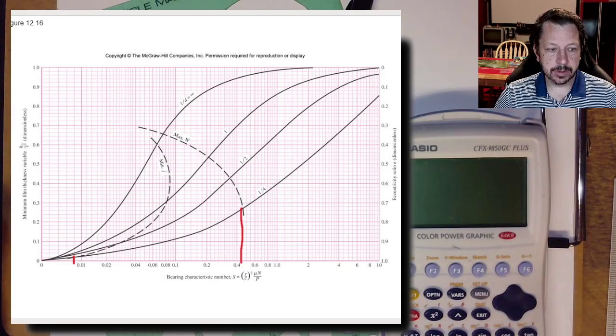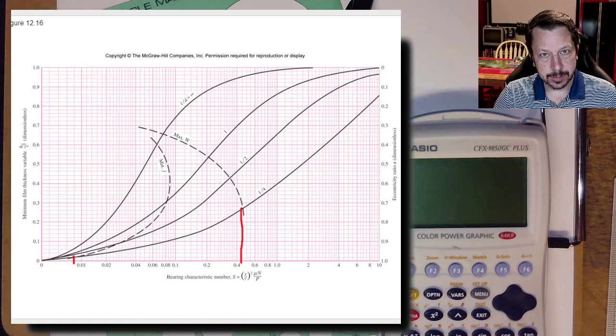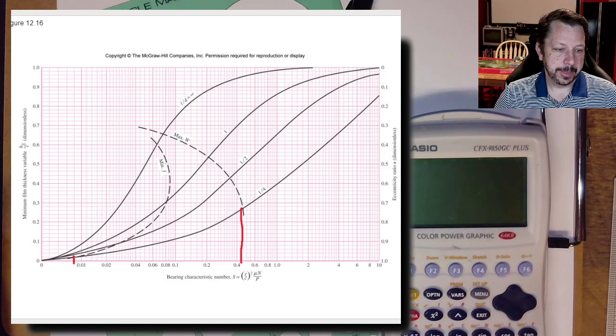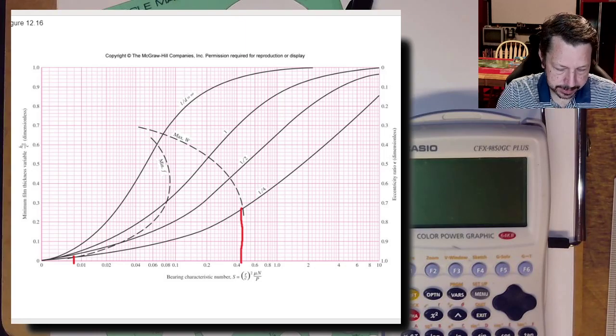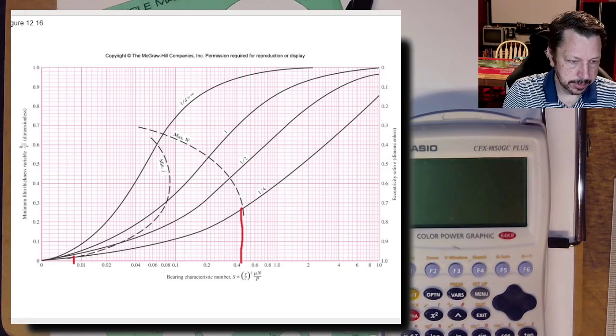And we get a little bit larger clearance needed to produce that. So here, there's a really tight clearance. This is maximizing the weight supported, so it's really compressing the fluid. Here, it's minimizing the friction, so there's more gap, so the fluid can flow easier. So I have two C values here. In fact, let's give them different names. Let's do C1 and C2 so that they're different numbers.